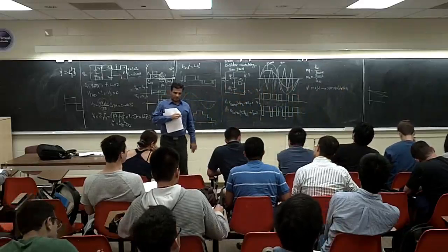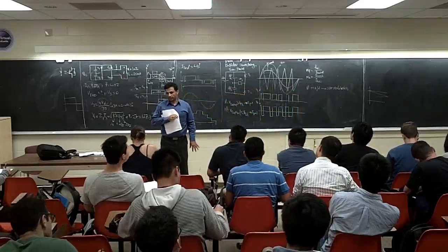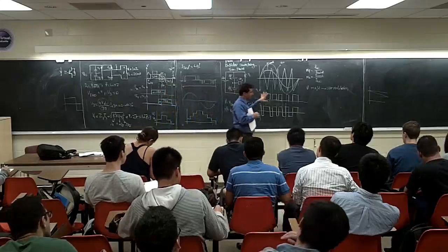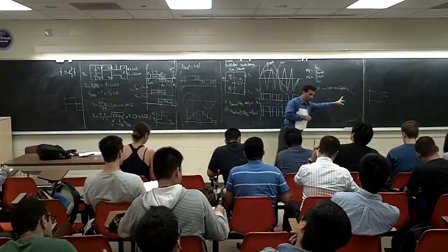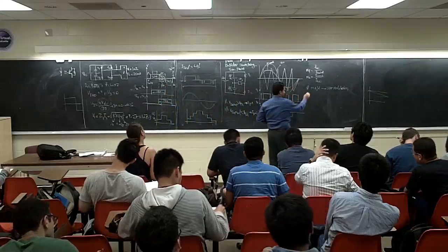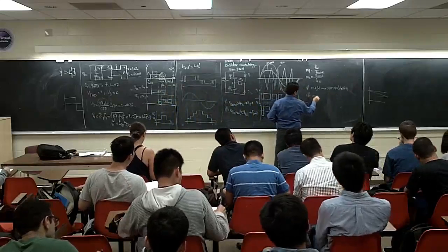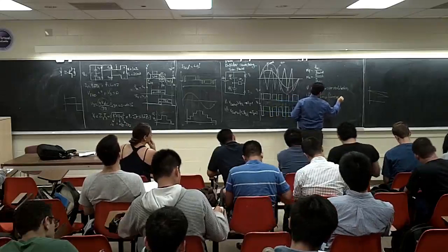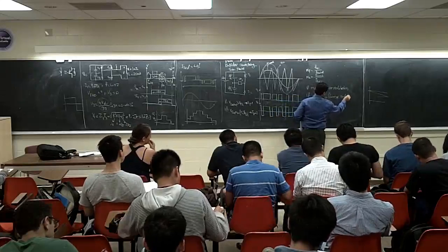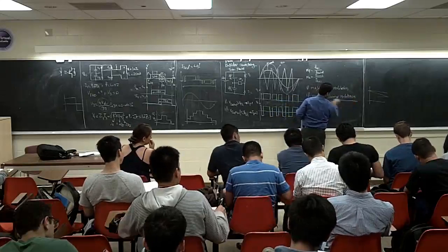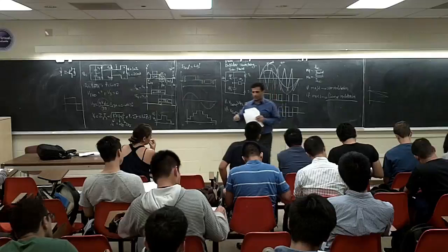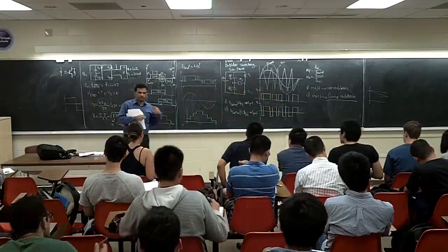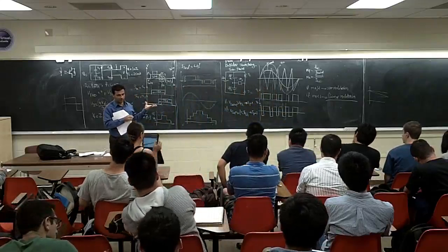We don't like overmodulation because the system is going to get some harmonics. But if we have to, in some cases, we have to go. If MA is more than 1, they call it overmodulation. If MA is less than 1, they call it linear modulation. If they are talking about linear modulation, you need to do some simulation to get a better feeling about what we are talking about here.